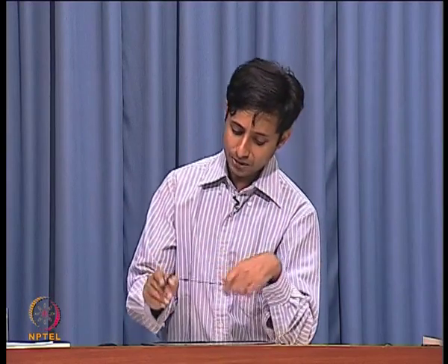A capacitor likes the voltage across it to be a constant, an inductor likes the current through it to be a constant, right. Now, what is going to happen is that initial current through the inductor is 0. So, the inductor is going to say I would like the current through me to remain 0, I do not want the current to change.